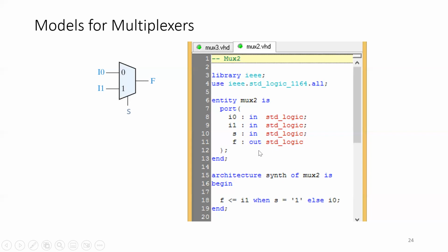I think you usually leave it without a semicolon. And in addition, this is entity MUX2. Sometimes it is accepted. In other occasions, I need to say end MUX2. If you get an error, you need to put here end MUX2. If it passes, okay. You have only one entity. But it is advisable to end MUX2.